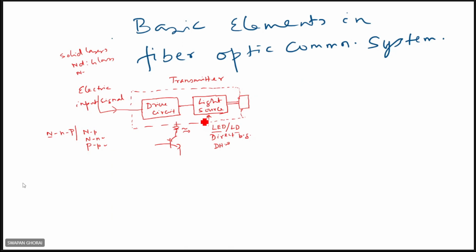But you see, these types of sources are used in optical systems. Next, there'll be the fiber fly lead. Actually, this is a small portion of fiber used. This is called fiber fly lead. A small pigtail of the fiber is used to increase the coupling efficiency. Sources are there, but during fabrication, a small portion of fiber is inserted so that maximum light can be coupled into the actual fibers.